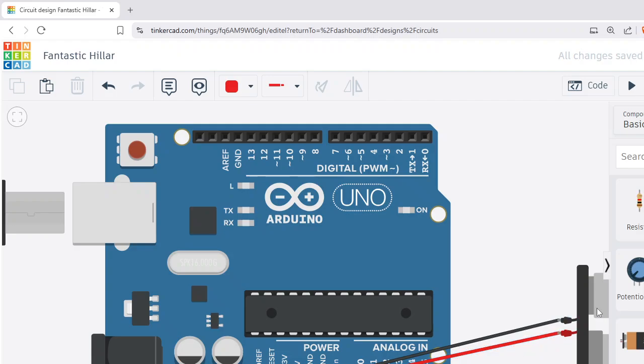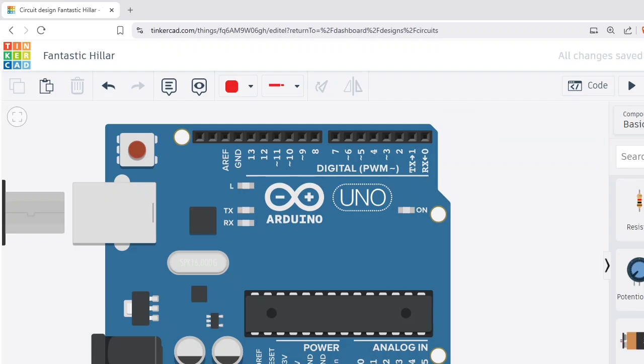Are we okay? Yes. So you should be very clear about these pins. Ground pins are basically earth pins. This is 5 voltage out. This is 3.3 voltage out. This is voltage in, and voltage in is normally 5 volts. Are we okay so far?